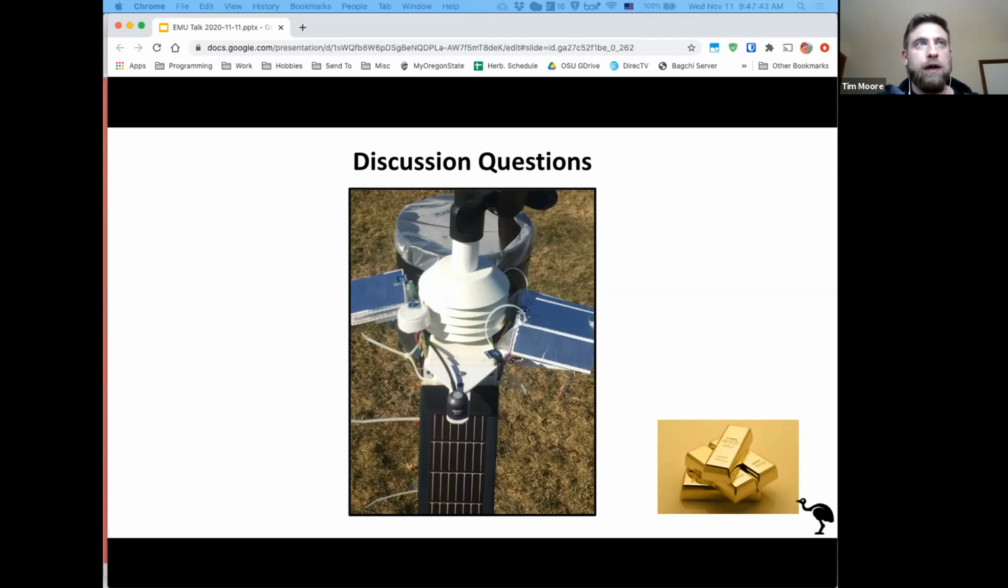It seems like more and more the industry is moving towards vane shields. Here, right in the middle, you can see these stacked upside-down cones. These are very commonly used temperature shields. But again, you can get air trapped or cooling inside there that may heat up and cause a lag effect in the temperature.